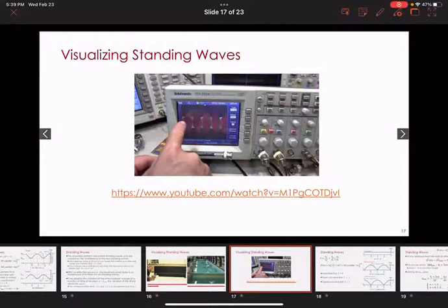He's going to get to this point here, which is still graphics of this. And what he's going to show is that the yellow one is like an incident wave, and he's got a blue one, it's like a reflected wave. And he adds them, because remember, our total voltage is the sum of the incident wave and the reflected wave. And that is this red one.